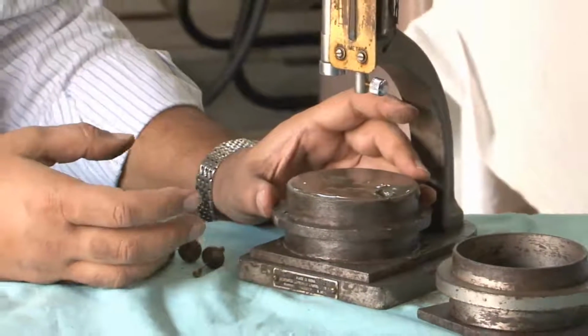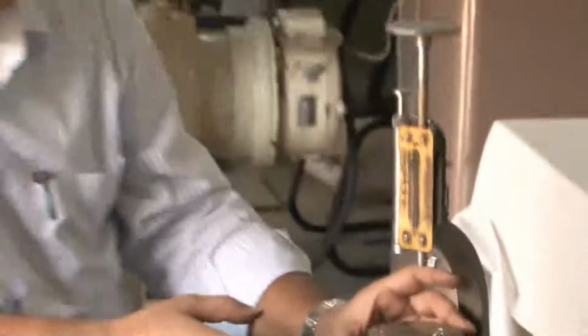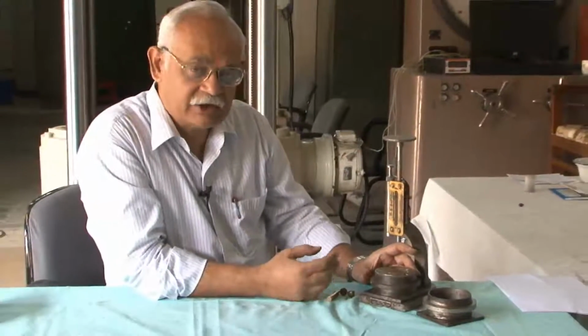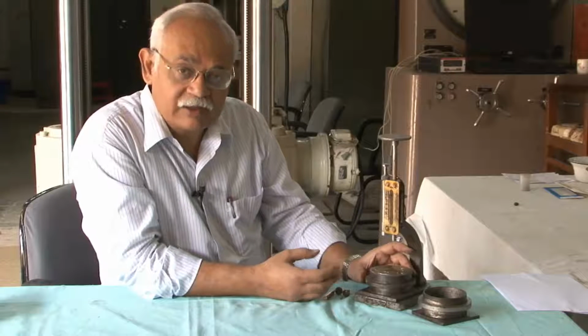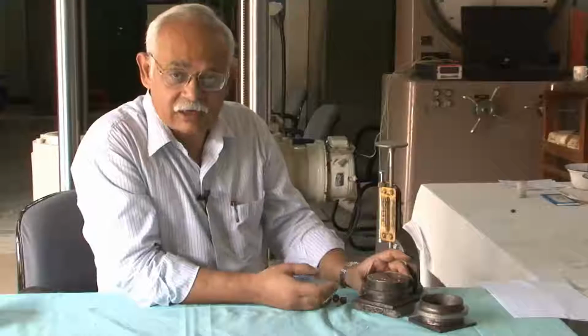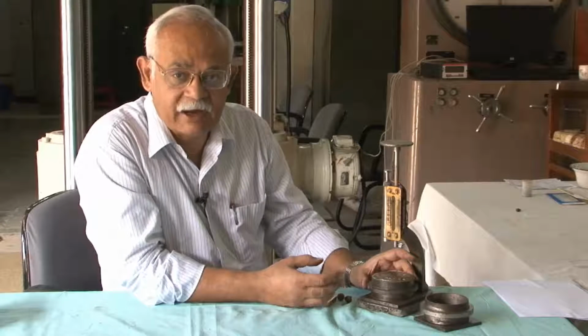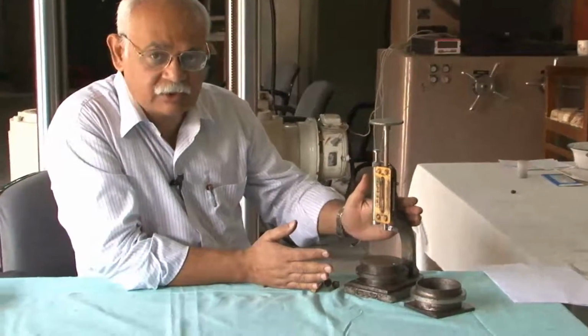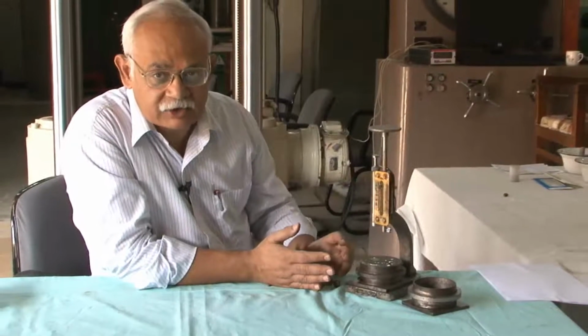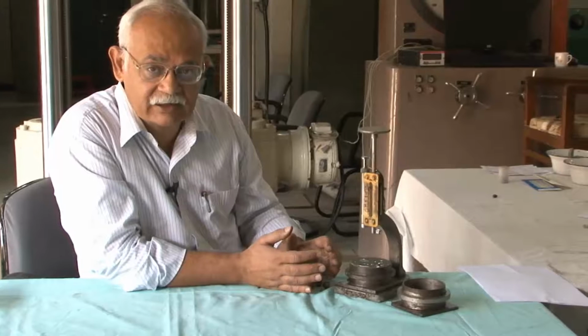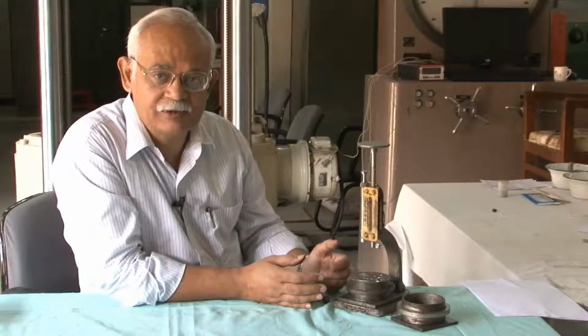This test can obviously be now modified or adapted to determine the consistency or initial setting time or final setting time of another cementitious paste, where the cement has been replaced by a pozzolanic Portland cement or any other chemical admixture or a mineral admixture has been added to modify the cement paste. So, the principle of penetration resistance remains the same. The same apparatus can still be used, except that the standards that we use, the specifications that we use, the test method and so on, they will change depending on what kind of paste is being used.